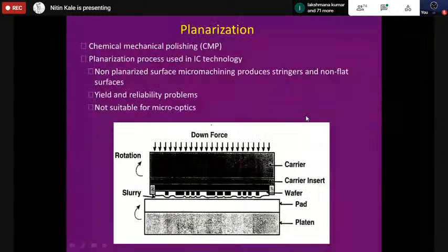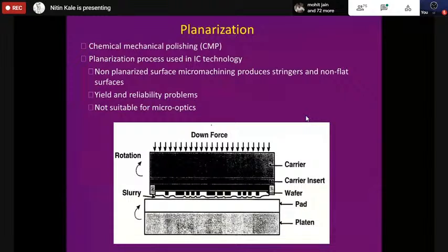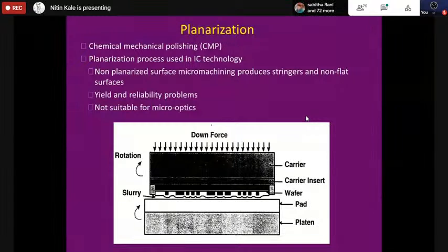There is a technique of planarization, where after etching you might have some rough edges somewhere, so you can planarize. You essentially have a plate which rotates, and you will have chemicals which are in the form of microspheres. Those would be used to planarize the surface.